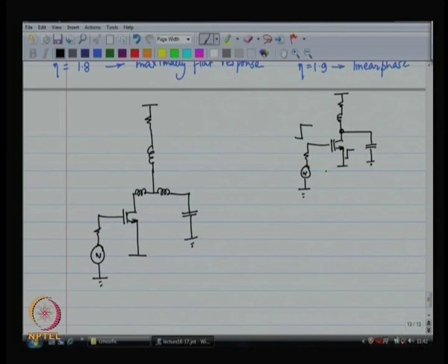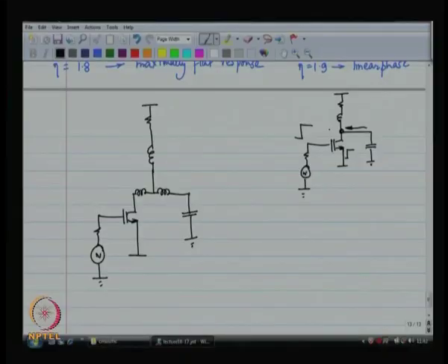So, when the current through the MOS device goes through a step response, what is going to happen is all of this current is initially going to come out of the capacitor. What was it earlier? When the inductor was not there, what was it? The voltage here was VDD. So, as the voltage would start dropping, current would come through the resistor, right, more and more current would come through the resistor. Now, the inductor is blocking current through the resistor completely. So, all the current has to come from the capacitor, which means that the capacitor is going to discharge faster. All right.